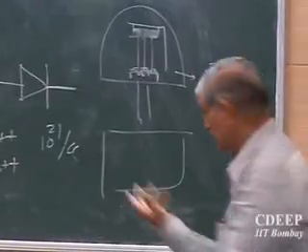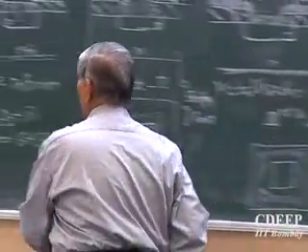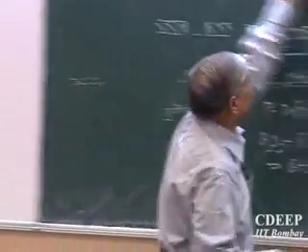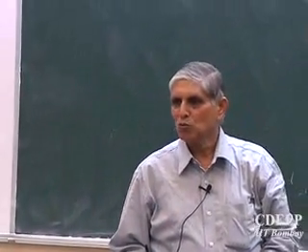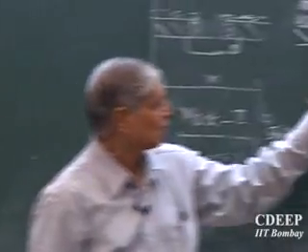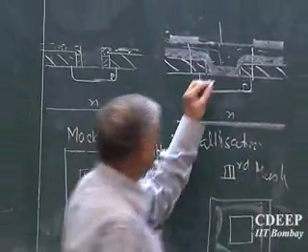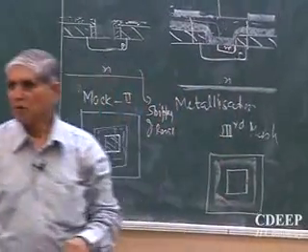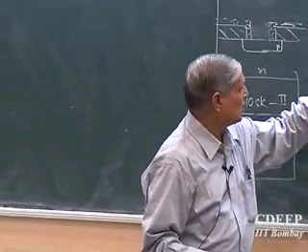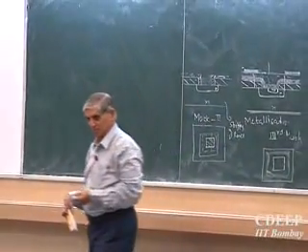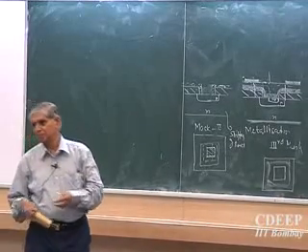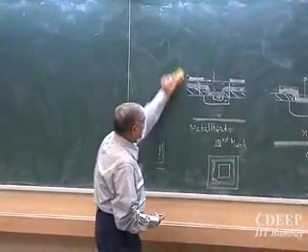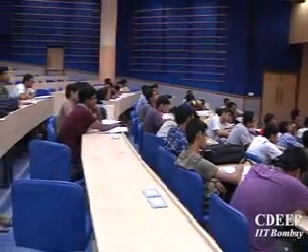The problem is something very interesting when the metal is there, because the metal can also go, so some tricks have to be used. Okay, so we saw today how to make a diode, and by an additional process step, what can we make? A transistor. What should be there before this metallization? I use a similar mask and make N plus inside. Then I need a contact here, and a contact here, to make 3 contacts. Keep doing masks. A transistor requires 6 masks to create an NPN. A MOS transistor also requires 6 masks. But in 4 we can make some rudimentary MOS. Normally we require 6.